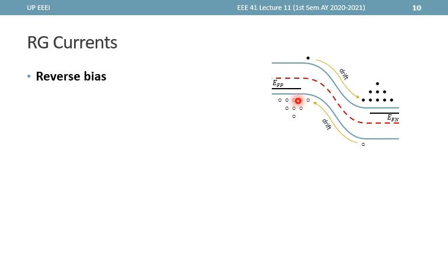What is our expected change if there is some RG happening within the depletion region? To begin with, which among R or G will be dominant in this depletion region? Note that we reverse bias the device, so there are fewer carriers present here than there normally are at thermal equilibrium, and therefore generation will be the dominant RG mechanism in the depletion region.